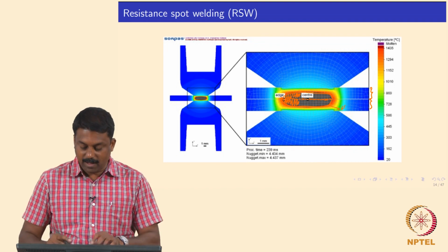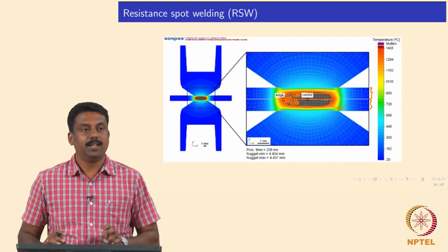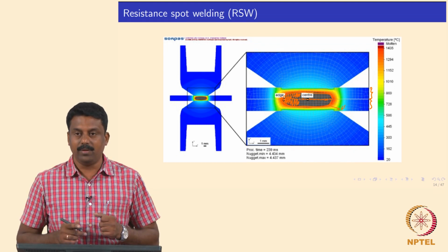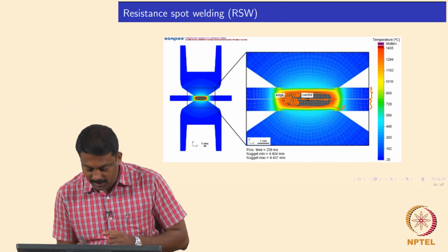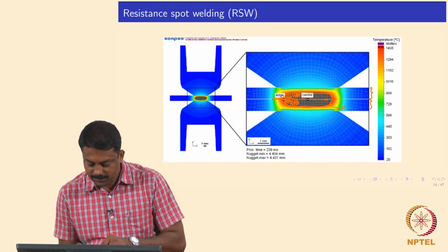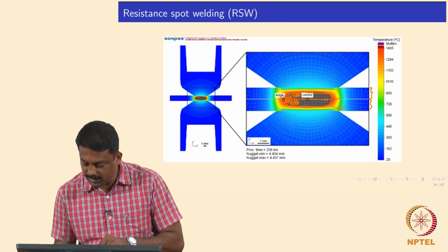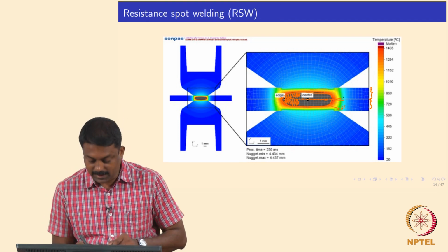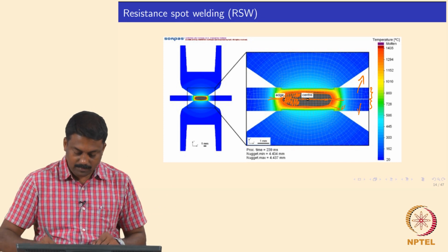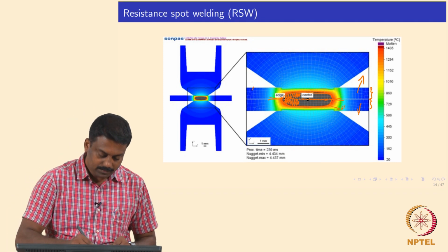Now, after welding, if you apply a load, say for example a tensile load or shear load, you already have an interface which is not joined here. So, this is like a notch, is it not? It is like a notch, and you pull the plates apart.